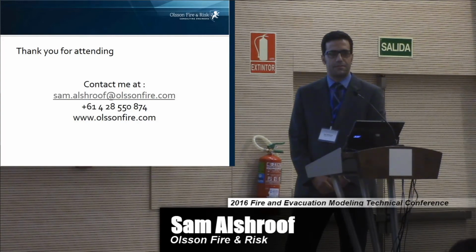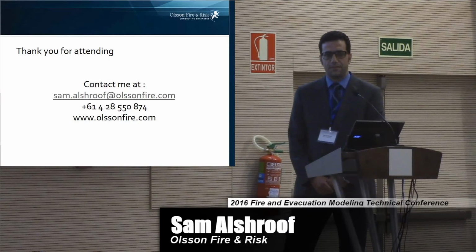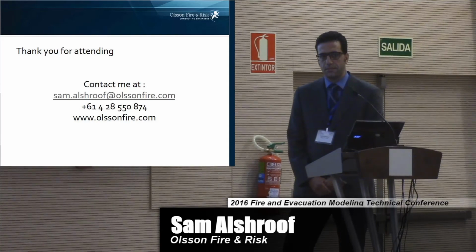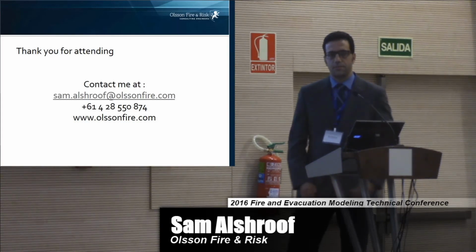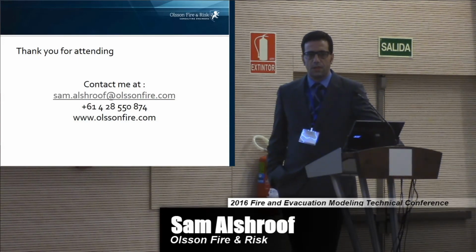One more quick question. To assess the mesh quality and the mesh resolution, there are some hints given in the FDS user guide, like the measure of turbulence resolution, and the evaluation of Y plus to assess the quality of the flow along a wall.